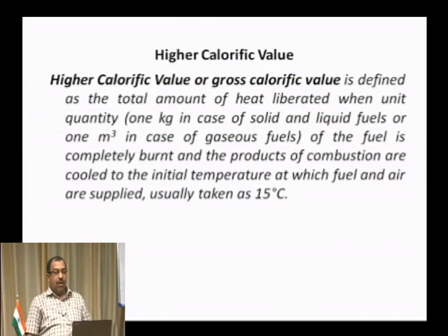Higher calorific value or gross calorific value is defined as the total amount of heat liberated when 1 kg of solid or liquid fuel or 1 meter cube of gas is completely burnt, and the products of the combustion are cooled to the initial temperature at which fuel and air are supplied. Usually the room temperature will be 15 degrees centigrade.